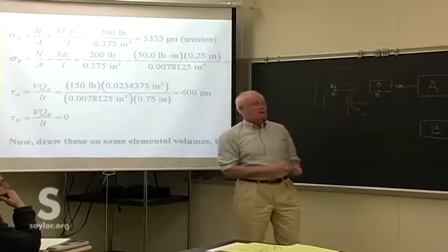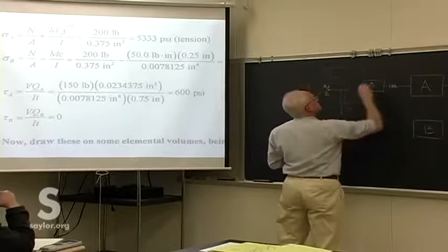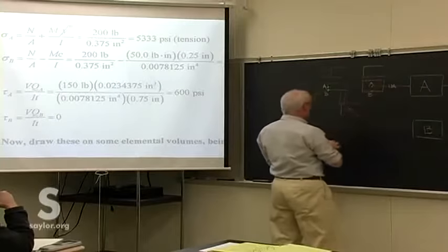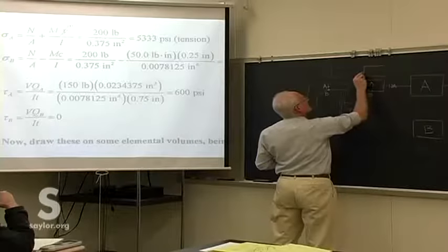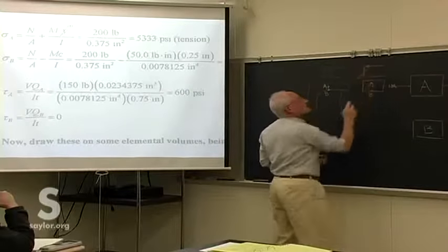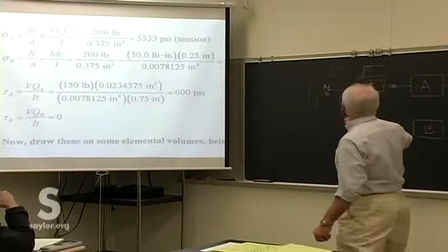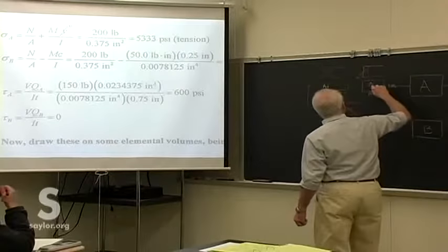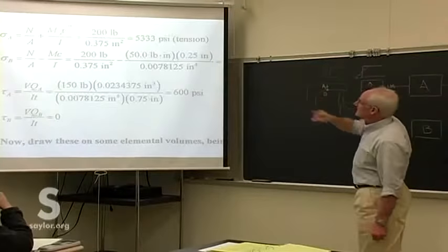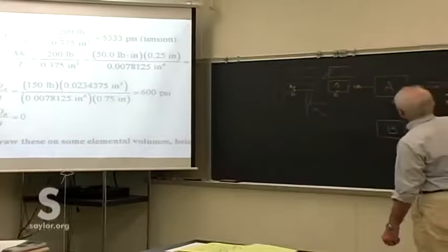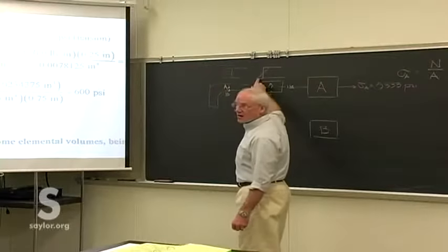And when we're looking at the bending stresses, remember those are, gotta keep my color scheme constant, those are linear across the cross section and varying linearly across the cross section, and 0 at the neutral axis. So this is point B down at the very bottom. It's got the maximum. That's why c is in there. The minus sign is in there. Oh, I guess I drew it the wrong direction, because these two are in opposition to each other.